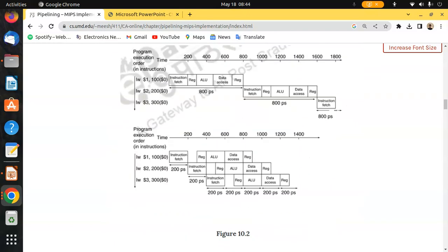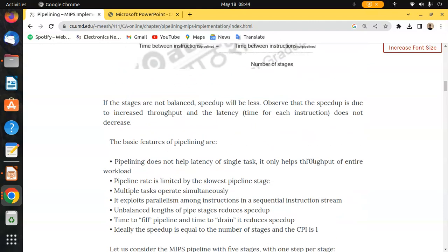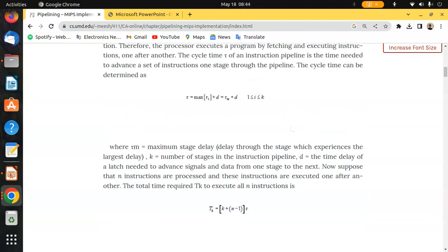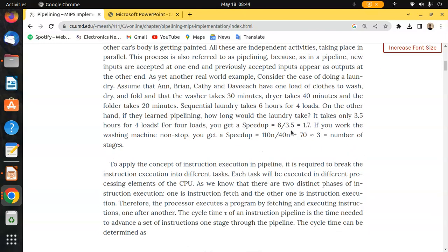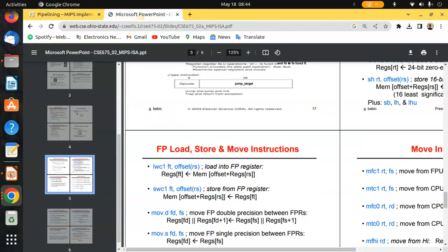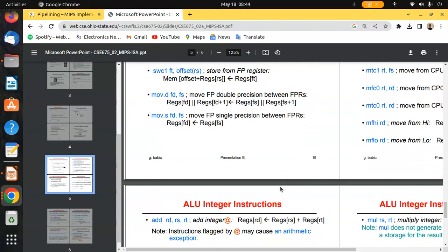So this MIPS 32 processor, what do we generally write? We give instructions in an assembly language program, right? And the assembler converts our input instructions into the corresponding binary or machine code. This MIPS 32 works on a 32-bit instruction set. So each program you type, be it add r0 comma r1 comma r2, or any other, is going to be converted into a 32-bit machine code.